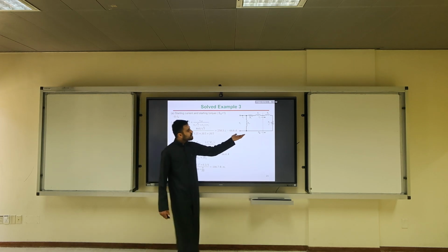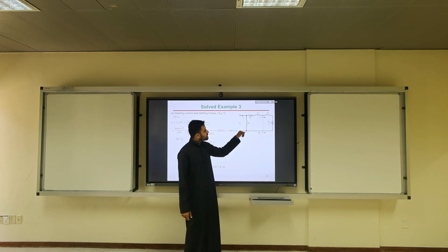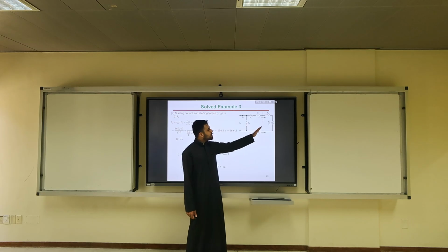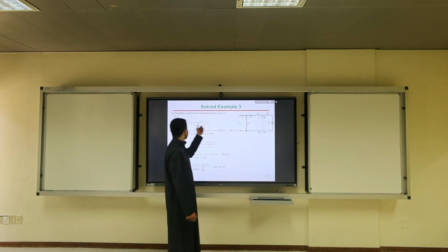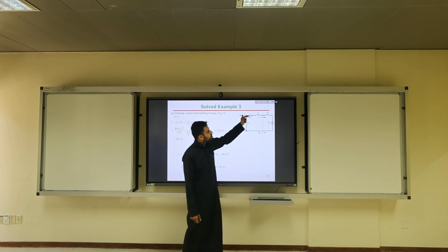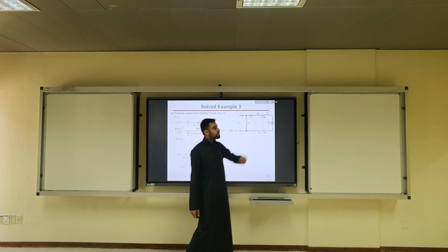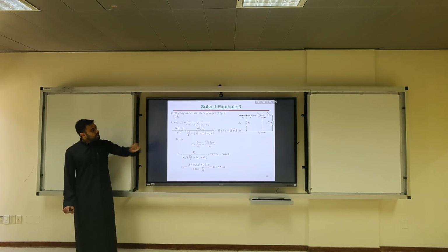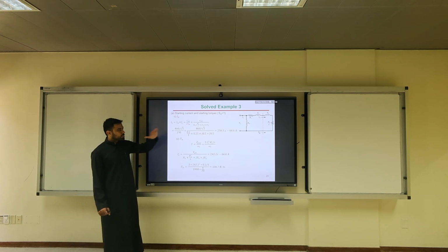I'm using the exact circuit. I don't have RC, and I'm moving the parallel branch ahead of R1 and X1. This makes my calculations faster because I can calculate I1 as the magnetization current plus I2 prime. This is EA. We're taking 462. I wish I could solve it, but we really do not have time. If you have questions, let me know.